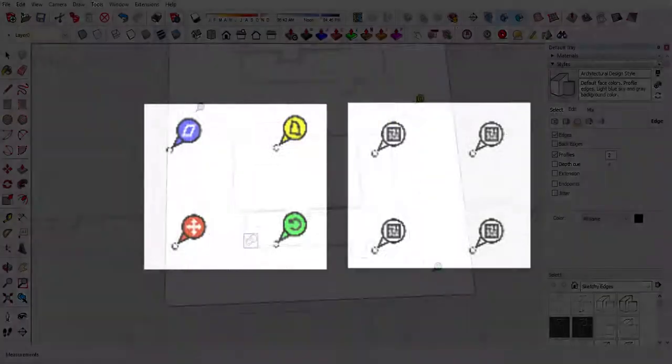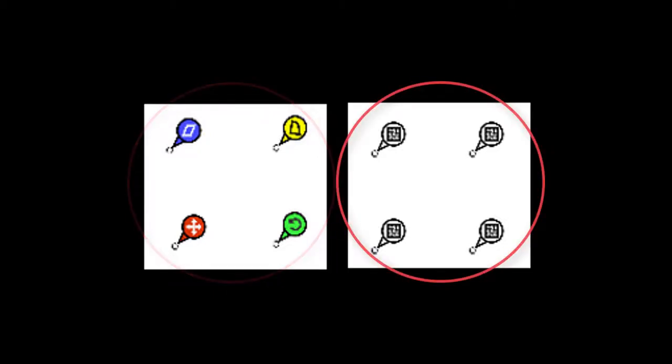Positioning images in SketchUp is used either in fixed pin mode or unfixed pin or free mode. In fixed pin mode, each pin is associated with a specific task. The red is used for moving, the green for scaling and rotating, the blue pin for vertical scaling or shearing, and the yellow pin for distortions. In unfixed pin or free mode, the pins are all acting freely and are represented with the same color. They do not have any specific task assigned to them.